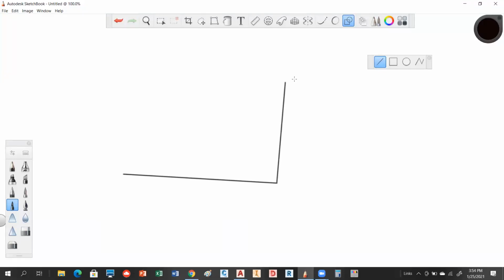Yeah. Okay. So if these lines, notice this line is not parallel with X. So that already complicates how that arc's going to work for you. Okay. Does that make sense? Unless you know what this angle is, and you can use the direction command to do that, but I still have to pick the two endpoints of that line to show AutoCAD what that direction is.